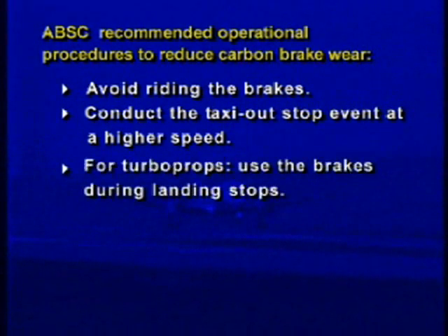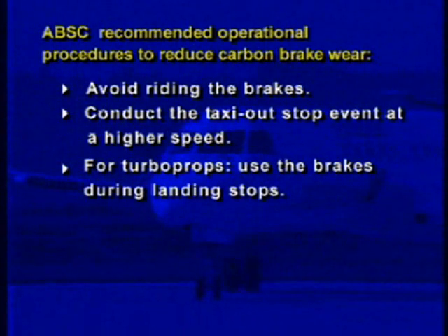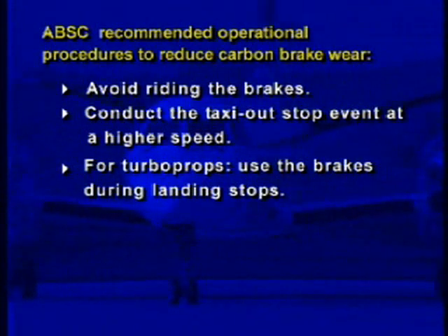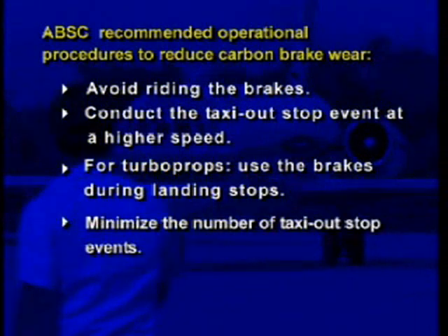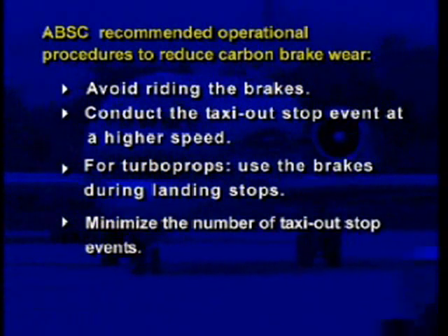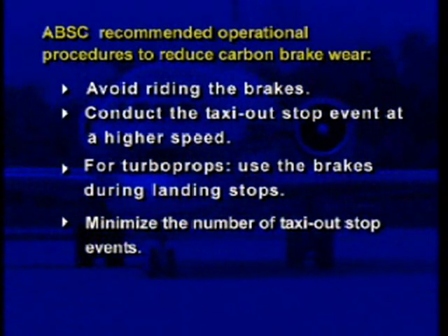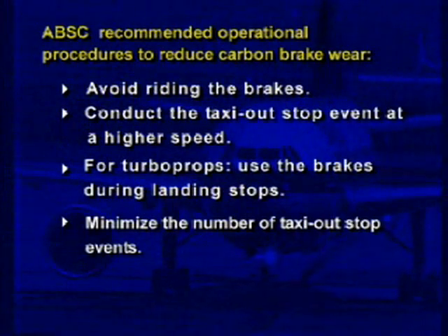For turboprop operations, we recommend that pilots use the brakes during the landing stop and not rely only on reverse pitch. The brake heat generated during the landing stop will reduce brake wear during the taxi-in procedure. Minimize the number of taxi-out stop events. Less stops equal less wear on the brakes.